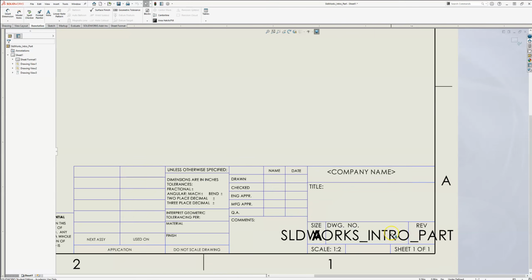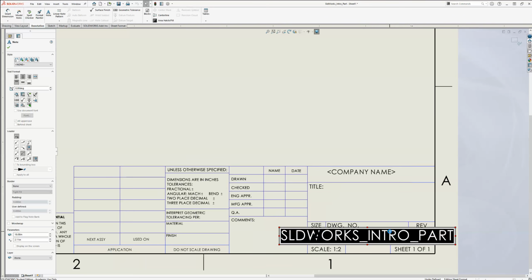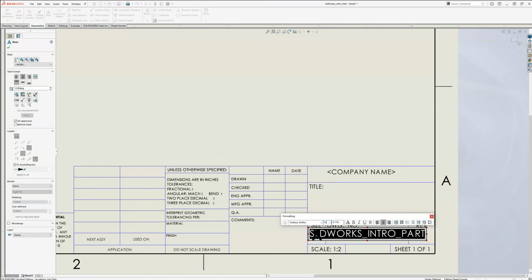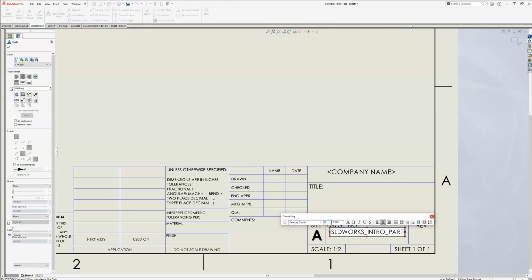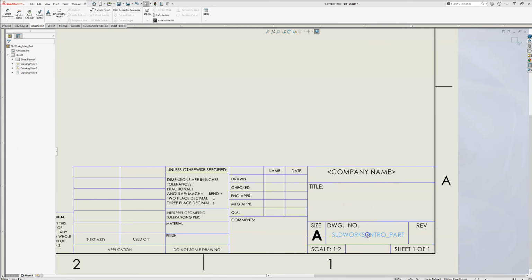And now you can see I can actually get down in the title block. So for instance, I could come in here and start playing with the size of this until it fits in the space. There we go, size 10, just like you're used to in other word processors. Notice some of these have links to them. As I hover over that, it says PRP drawn by. That's kind of outside the scope of what I want to get to in this video, but that allows you to reference custom properties either in the drawing or the model to actually drive that value in that note field.